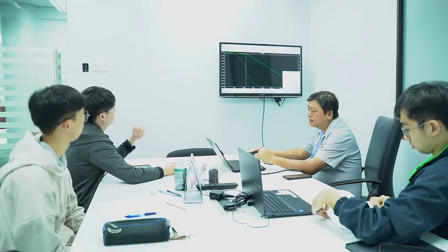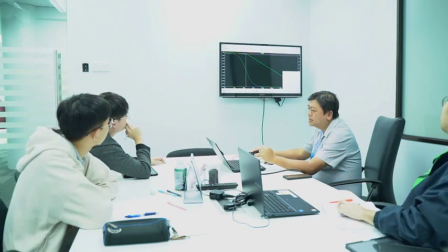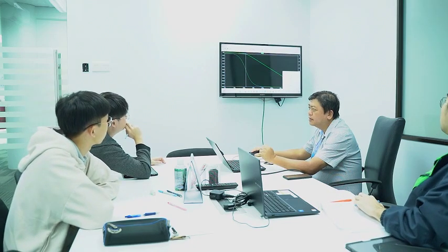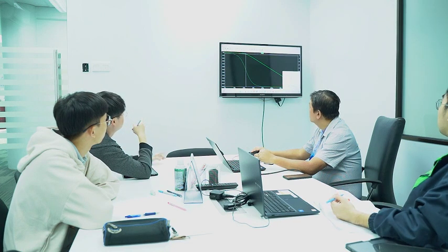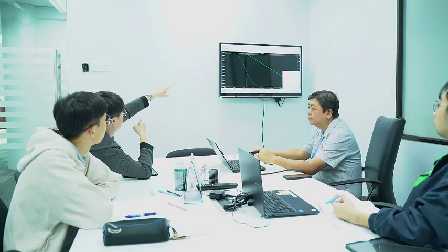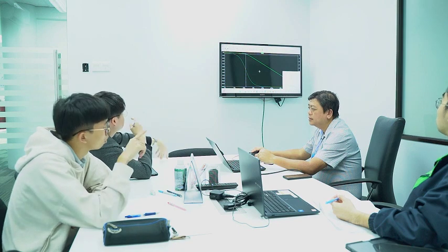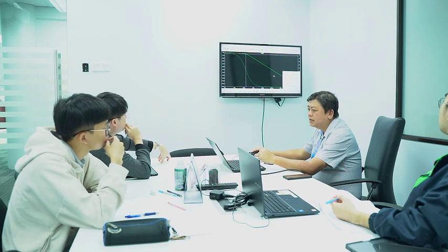It's about 160 hertz, right? So how can we get this value? Through when you cross it, I mean on the x-axis. Yeah. So from calculation, how to get it? It's f equal to 1 over 2 pi RC.